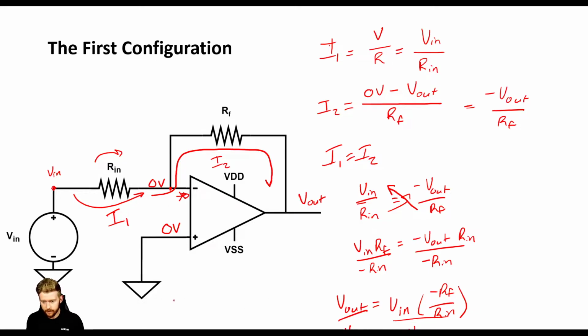And what that's going to give us is V out over Vn is equal to minus Rf over Rn. So V out over Vn, that's the ratio of our output to input. So that's kind of like our gain. This amplifier is going to have some sort of gain or attenuation. And if we want a large gain, then we need to make sure that this ratio of these two resistors is also large. And like we said before, there is this negative sign here.